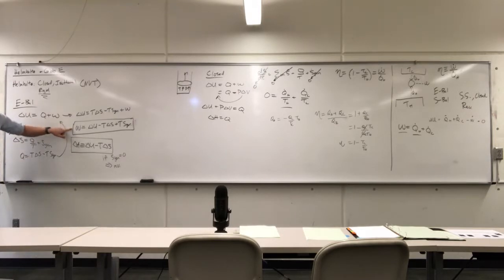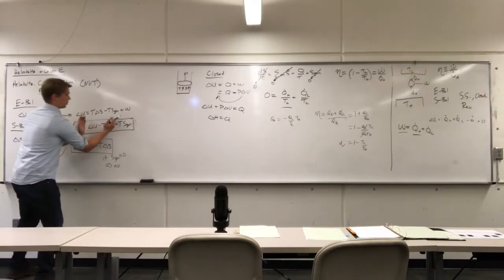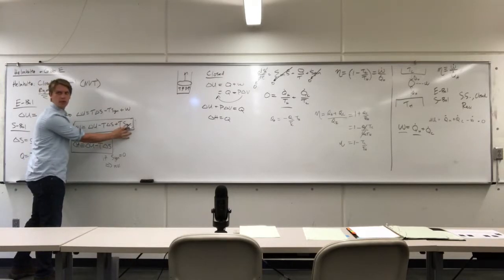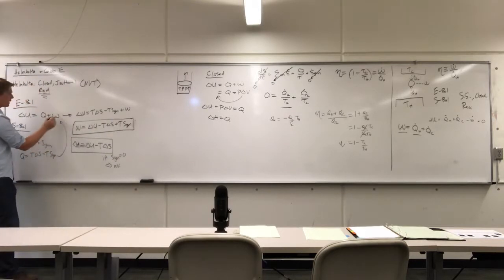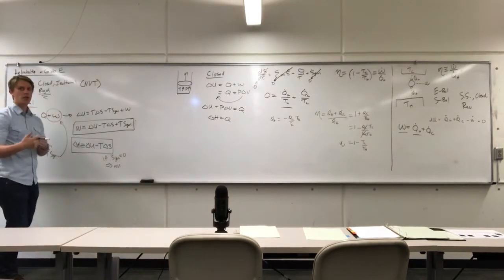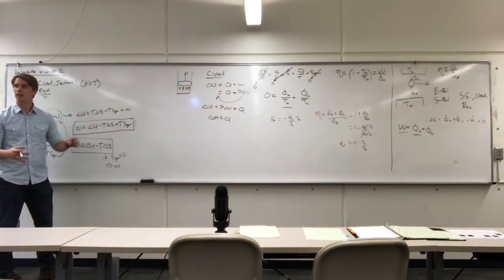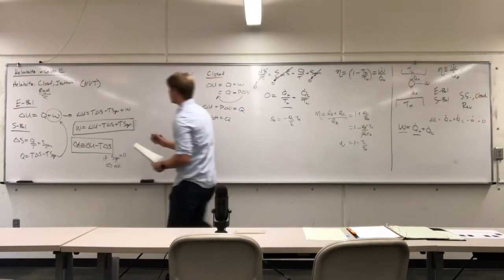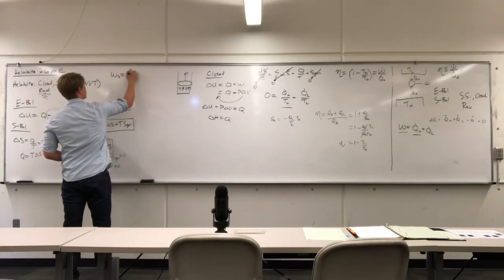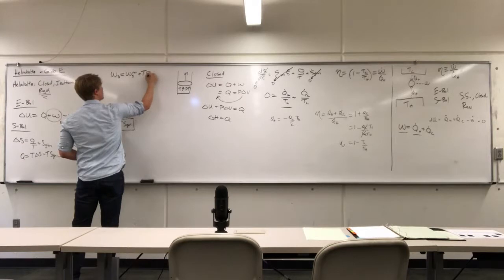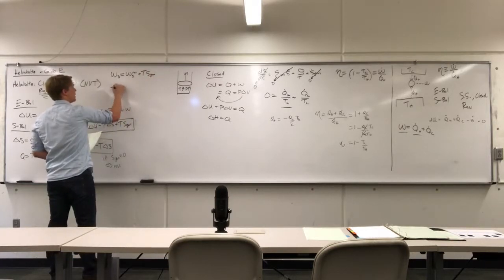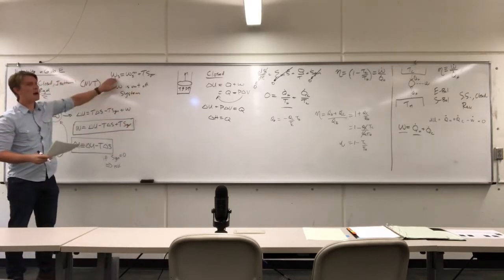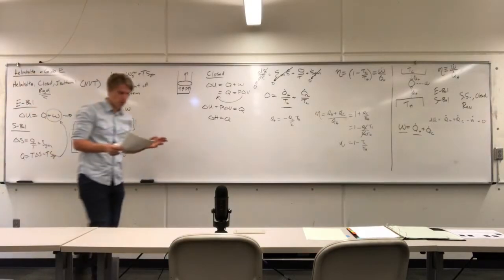Now, when we derive it including entropy generation, this contribution here is the reversible work. Here we're adding this T S gen, temperature times the rate of entropy generation. However, in this case we've defined work as positive going into the system, so negative work is the work that we want to get out. So having this positive term here basically means that when you generate entropy, you are always going to have less work coming out of the system. So another way to write this then is that the work that we can get out of the system is going to be the reversible work plus this T times the entropy generation. In this case, negative work is out of the system. So when this is more positive, that means you're getting less work out of the system. At least that is the objective of what we're trying to accomplish.